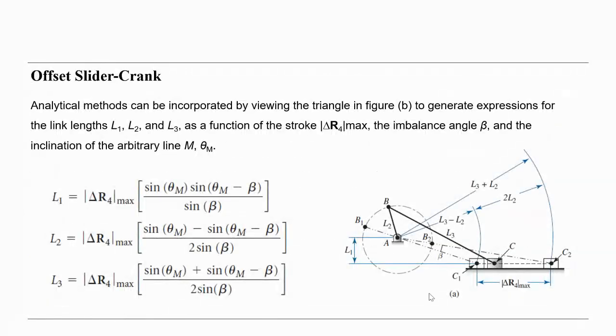That means I drive the crank, the L2, clockwise or counterclockwise, and I calculate the position of C and see how the position of C is changing with respect to the driving angle or driver angle.